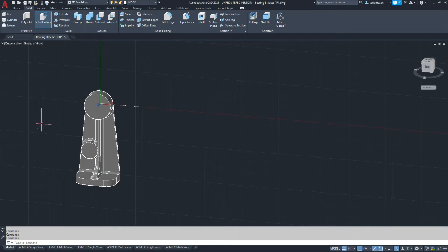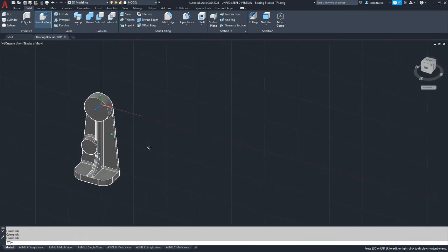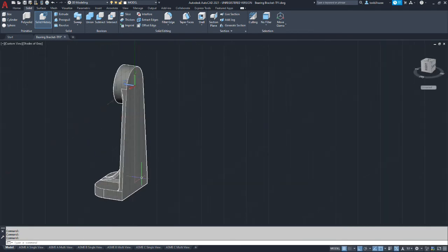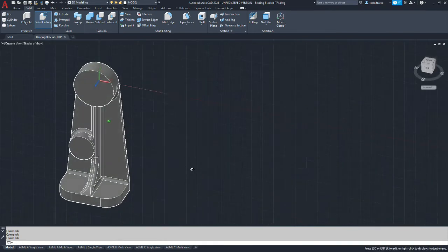There's several ways you can define it. You could also select on 3 points to define a plane. So, I could pick on my construction lines as my 3 points because they happen to be in that same plane. If your mirror plane doesn't contact the part itself, you're going to end up with a space in between based off the placement of that plane.